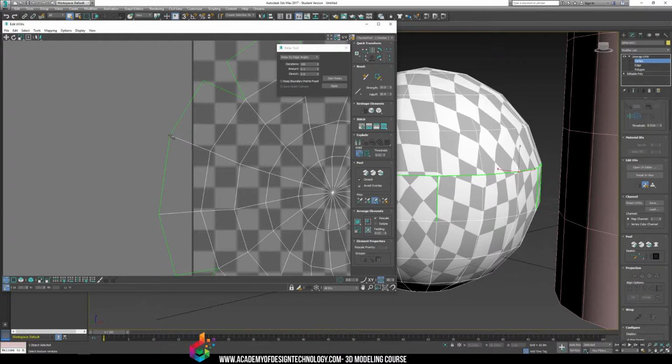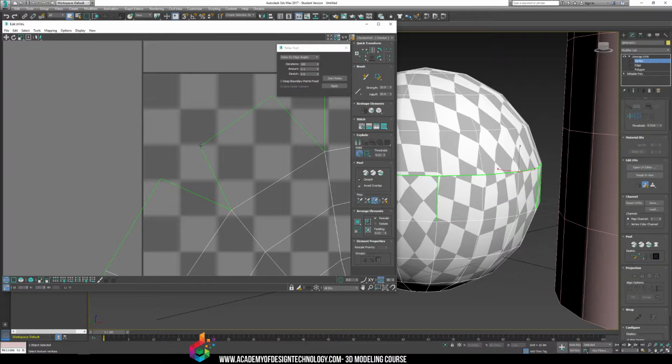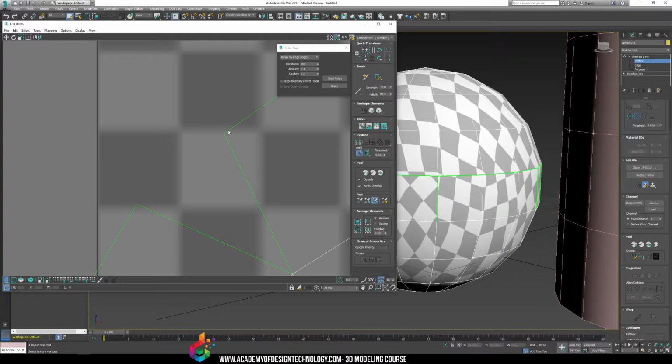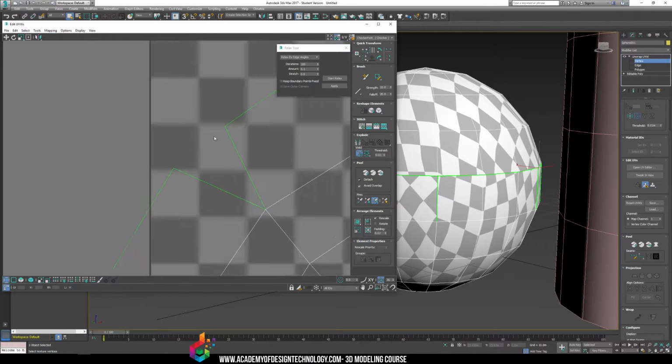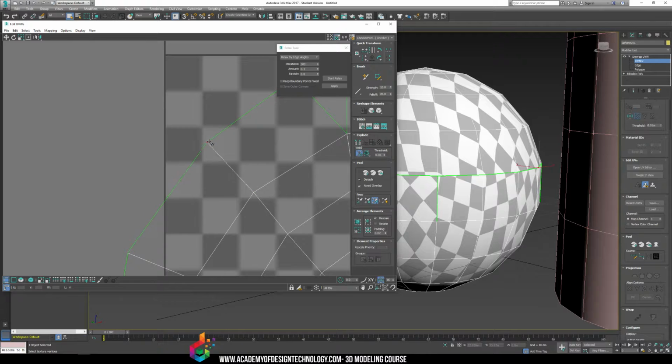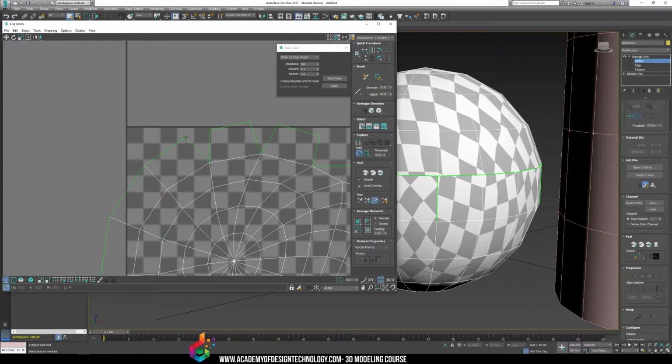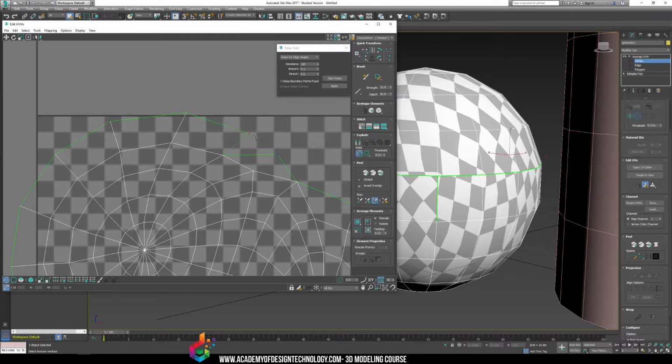and drag it together. And the reason why I can tell that these two belong together as one vertex is if I click on one, the other one turns blue, which tells me that this vertex and the other vertex here, they actually belong together and are a single vertex in my 3D space. So that's why I'm just going around and merging them. You'll notice the green lines are starting to disappear, and that's because the seam line is now disappearing. You want as few seams as possible in your 3D model so that your texture doesn't look distorted at all.